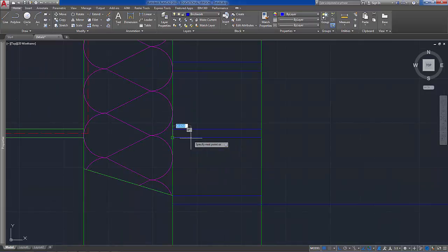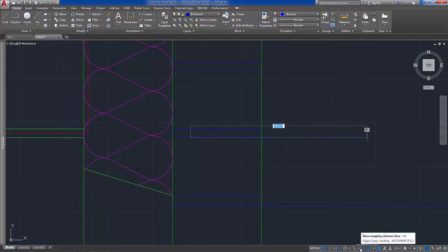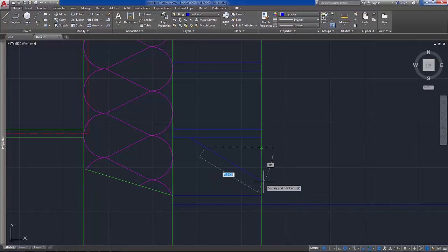So let's draw a line over by 20 millimeters, and then draw a line down at an angle. So let's actually use ortho instead, and have a line maybe across this way in some point. Let's see, just offset maybe by 20 millimeters again on the front here.